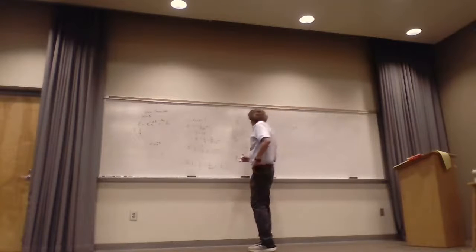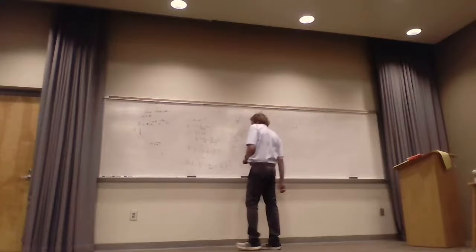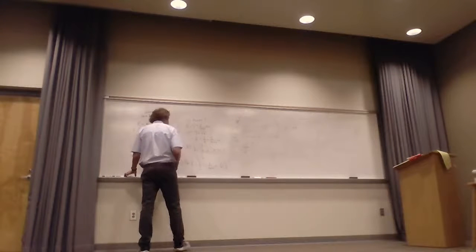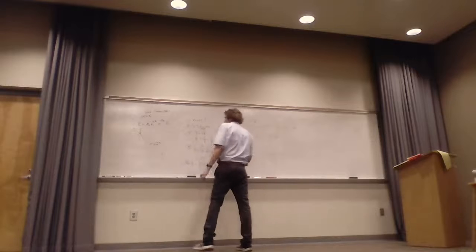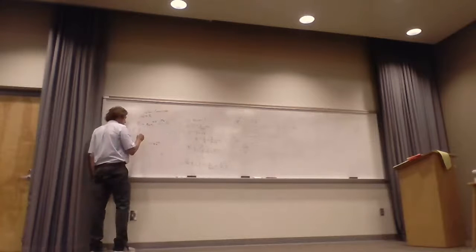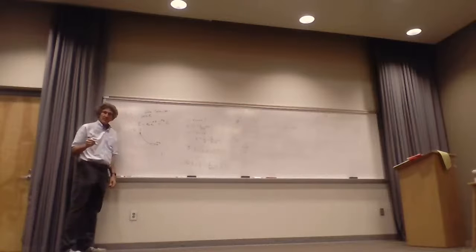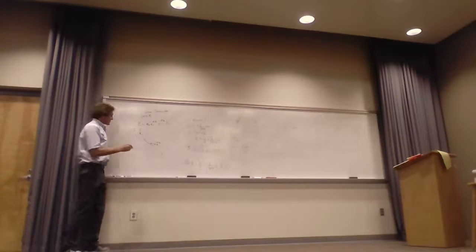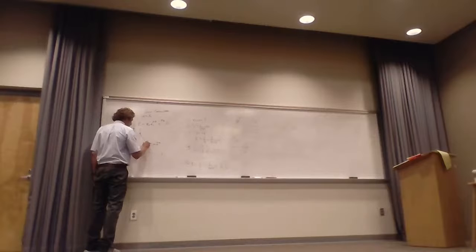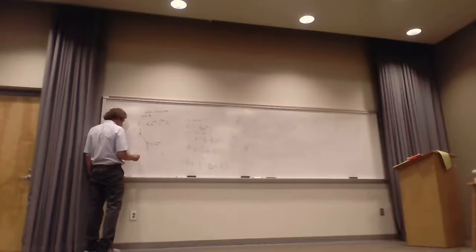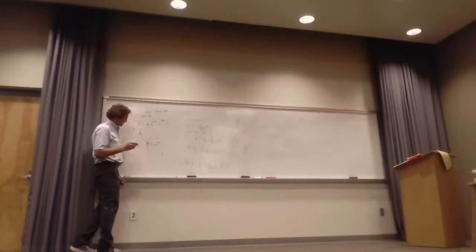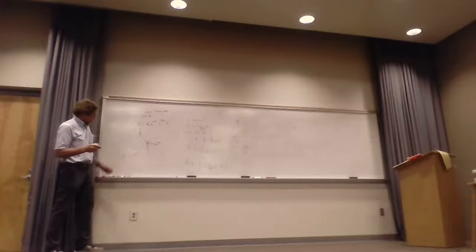Now, here's something that happens when we have a good conductor. We take a look at this and there's an E field on the surface, but we know that as the E field penetrates in towards the center of the wire, it's decaying. Do y'all see that? Right? But we term something, we call it the skin depth. We talked about something called the skin depth, and that's where the value here goes to e to the minus 1, all right? Its original value.